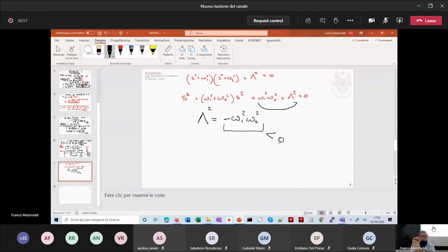The panel flutter is only flutter, it is not panel divergence, it is panel flutter, period. The model is not able to give you a steady instability solution, okay? Whereas the buckling is exactly the opposite. In the buckling instability, you may have only static instability.